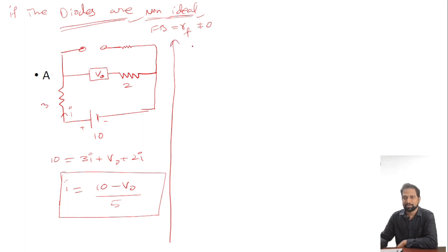And going to the applications of diodes: Zener diode as a voltage regulator. Remember, the total current is the Zener current plus the load current. Sum of the two we have to take. There are two possibilities that you should understand. Case 1, when the supply voltage is varied,